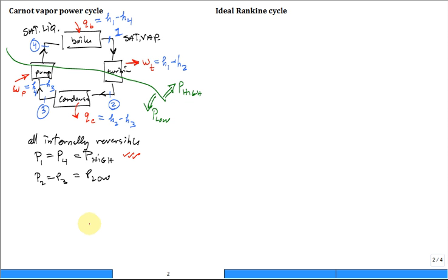All right, so it's been a while maybe since you plotted a temperature-entropy diagram. Long weekend, I guess, or something longer. What is that? A dome. What's under the dome? It's two-phase, liquid-vapor. What's the point at the top of the dome? Triple point or critical point? CP, critical point. All these states going down this side? Saturated vapor. On this side? Saturated liquid. Okay, let's put a line of constant pressure, the high pressure, and then another line of constant pressure, low pressure. What does that look like on a TS diagram?